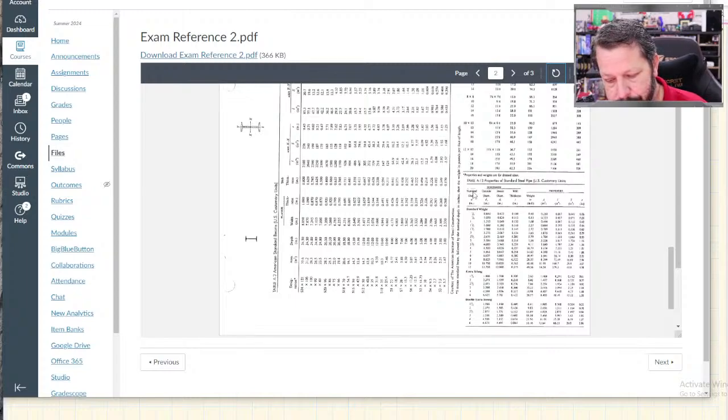And so what these are is if you're given a nominal pipe, say a 1-inch nominal standard weight pipe or a 1-inch extra strong standard steel pipe, then the 1-inch part is just its name. You have to go into a chart like this to see what the actual outside and inside diameters are.